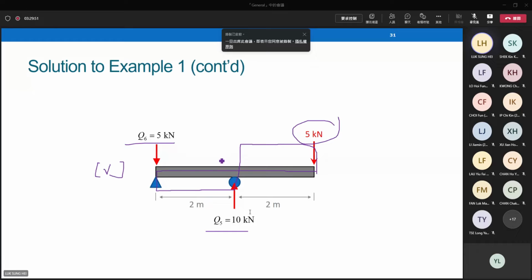For the moment diagram, you can also use your drawing techniques. But to draw moment diagrams, you have to pay great attention to the sign. In the past, when we taught how to draw moment diagrams in the structural analysis module, we drew the moment diagram on the compression side based on the derivations. But when you learn to draw the moment diagram in the design module, we will probably draw it on the tension side. Be careful about the definitions.